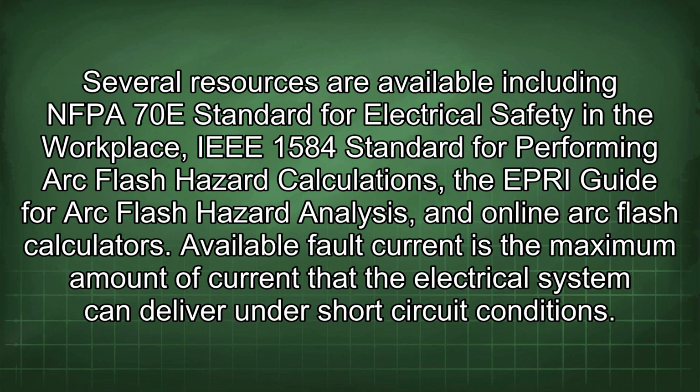Several resources are available, including the NFPA 70E standard for electrical safety in the workplace, the IEEE 1584 standard for performing arc flash hazard calculations, the EPRI guide for arc flash hazard analysis, and online arc flash calculators.